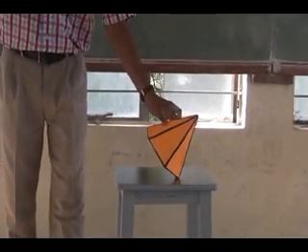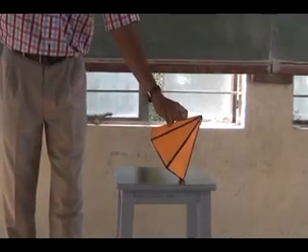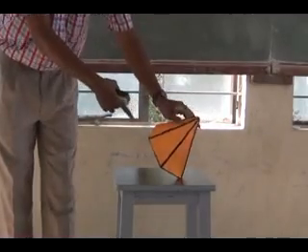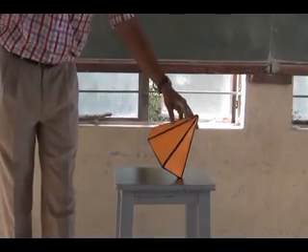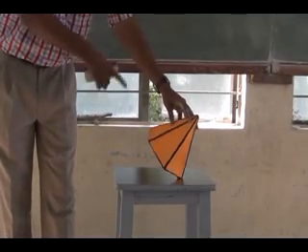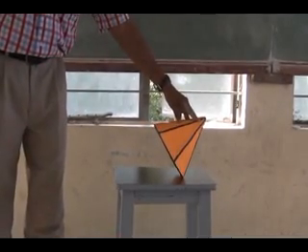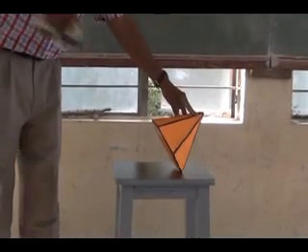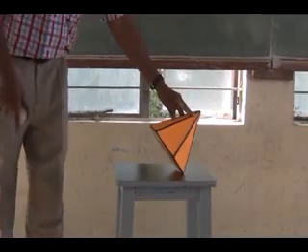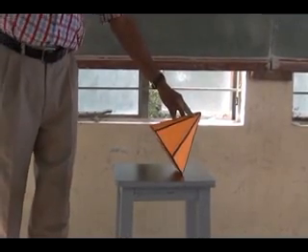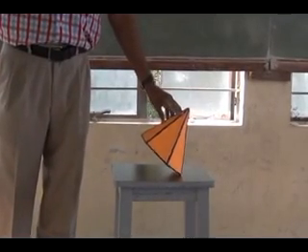Now one more condition is given. The base is inclined 50 degree to HP, also it is perpendicular to VP. If this is the orientation, then how about the base? Is it perpendicular to VP? No. It is inclined somewhat. The base is inclined to VP. So if I keep it like this, in this orientation, the base will be perpendicular to VP. That means the axis is parallel to VP. So both details are hidden in this problem.